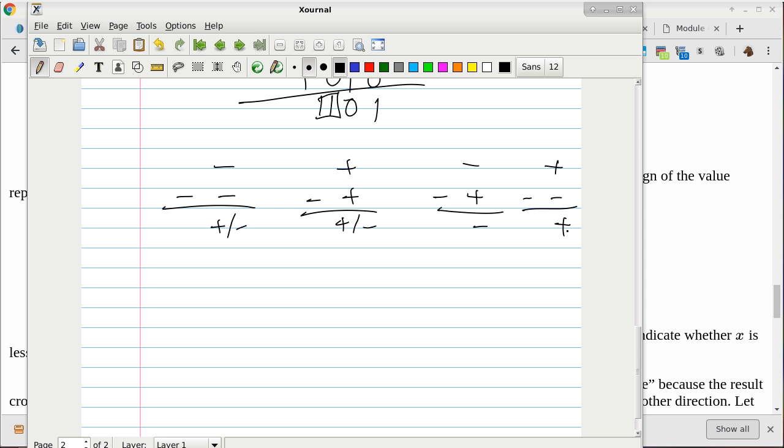When we are subtracting a positive number from a positive number, same situation. So the real problem has to do with the other two cases. When we subtract a negative number from a positive number and end up with a negative number, we know there's an overflow. And when we subtract a positive number from a negative number but end up with a positive number, we also know we have an overflow situation. So we have to find a way to detect that.